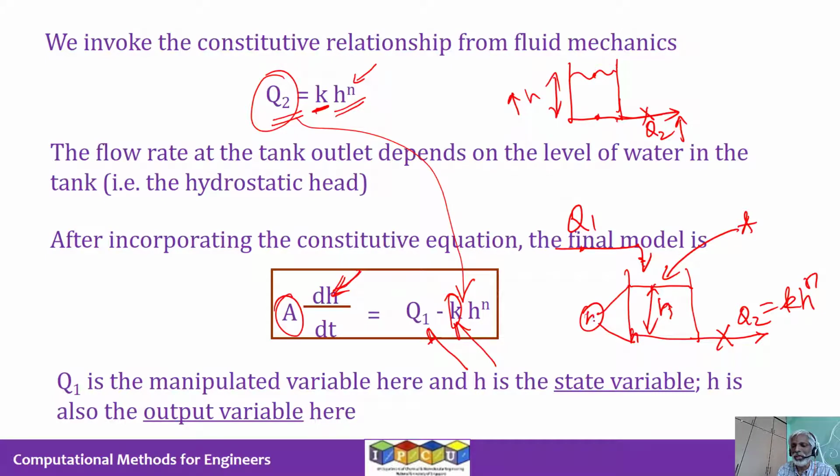So you measure the actual height, and then you can compare this height with the target height, what is called the set point or the target. This is nothing but the target height, the level at which you want the water to be in the system. So this is the plus sign, this is a minus sign. If there is a difference between HS and H, H is the actual height that you measure currently, and HS is where you want it to be.